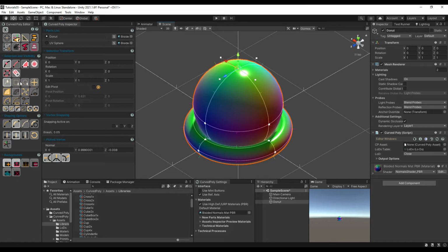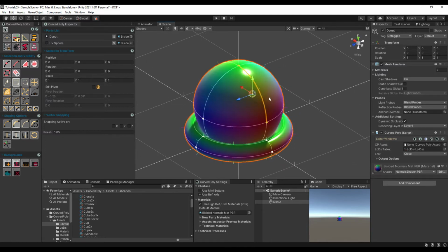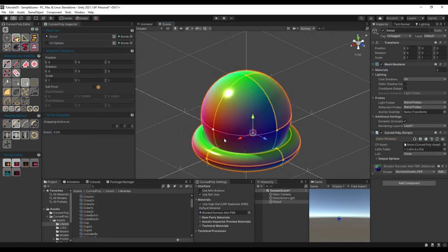With the Rectangle tool we can select more elements at once, by dragging a selection rect on screen. Again, the overall selection depends upon the selection mode chosen. For instance, if Vertices Selection Mode is active, and the rectangle is dragged over the 2 vertices at the extremes of an edge, then both the vertices, and the edge, will be selected. Same thing for the vertices of a polygon. The Circle tool works in a similar way. We can drag the circle over the elements we want to be selected, and we need to press the P or O buttons on the keyboard to reduce or increase the size of the circle.